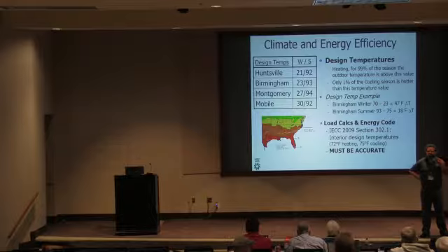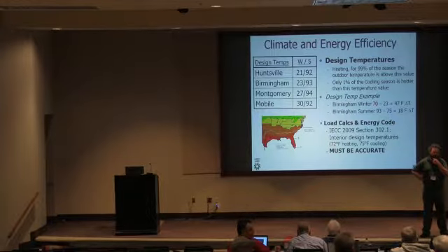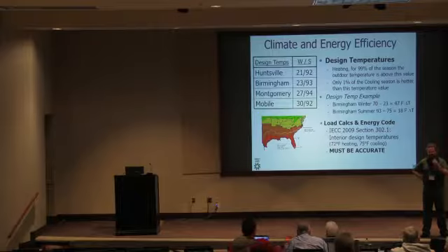Okay. Has anybody looked at, when spray foam goes in, if you're in a high radon area, finding that the house is more susceptible to higher radon levels than a house with normal insulation? You could see that problem because you made a tighter envelope. In general, the state of Georgia, and specifically the metro area, is a high radon zone.